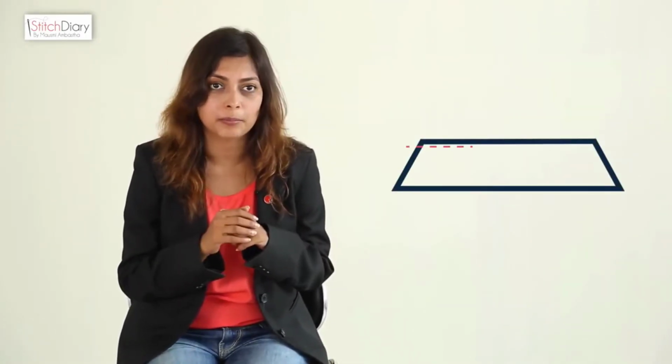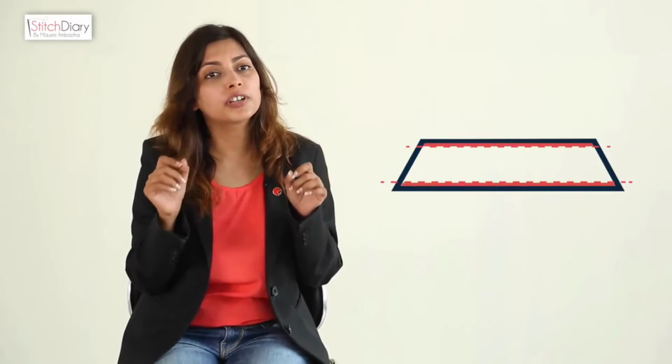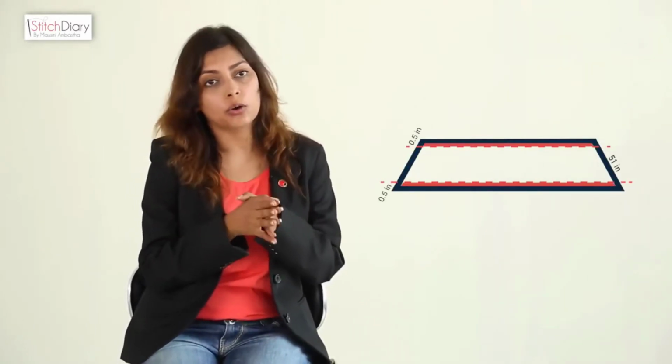The next loss we are going to talk about is edge loss or width loss. The only way to use fabric properly is to use the entire cuttable width of the fabric. So you need to measure your widths and then make markers accordingly. I know what you're thinking. You never get fabric in one width. There are various variations in the width.